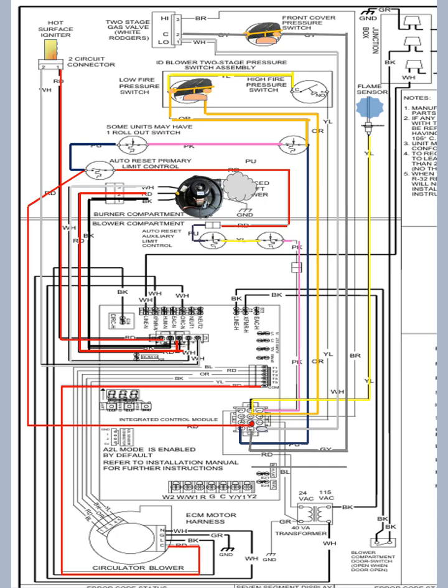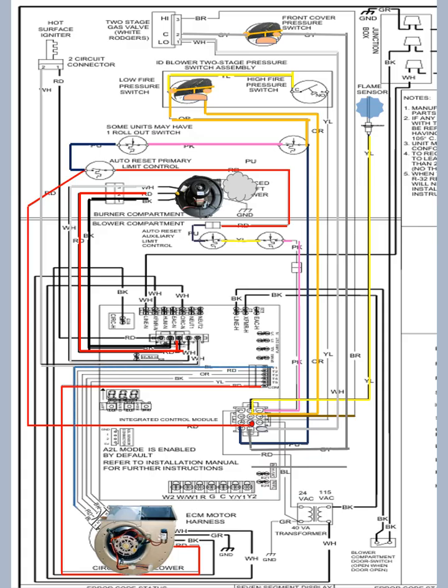Now we have ignition. The igniter is de-energized as soon as the flame is sensed. After 30 seconds, the indoor blower motor is energized on first stage heating speed.